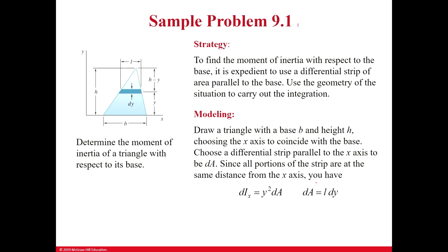So this is a problem right here that is not a regular geometry because it's not a rectangle. It's not a triangle with a right angle. It's a specific type of triangle that is not uniform. We know by now that we find the inertia in x with y squared dA.